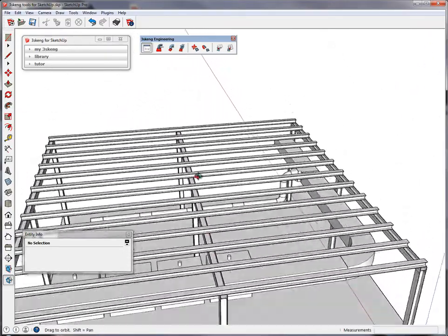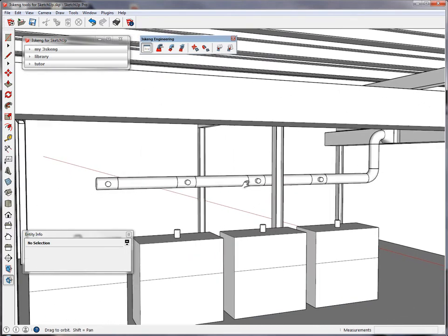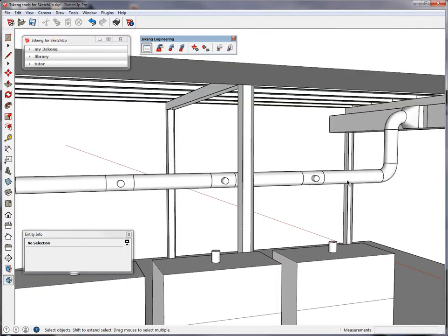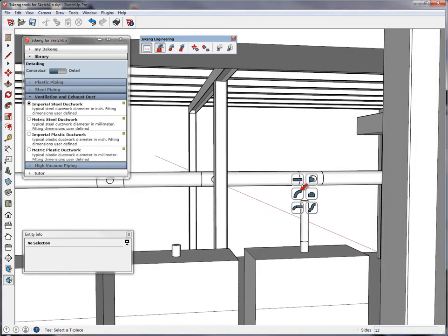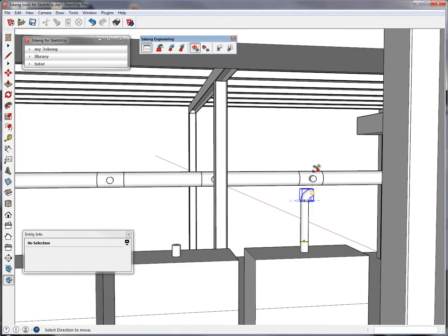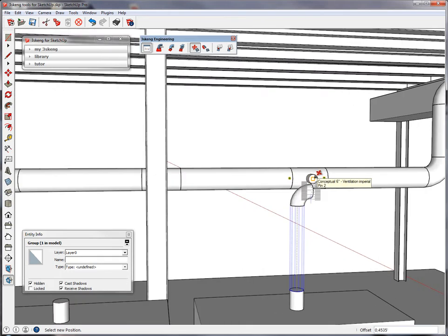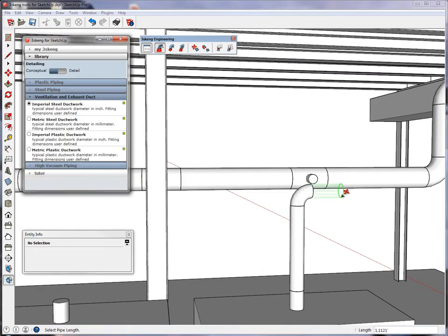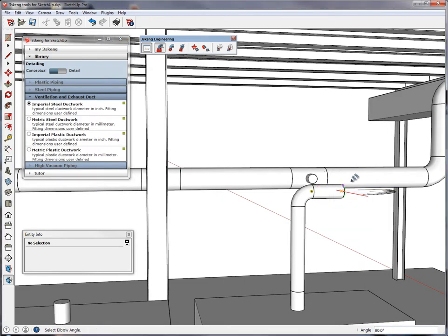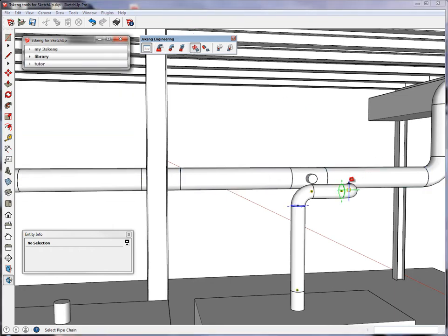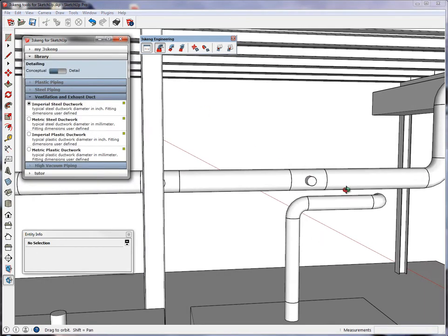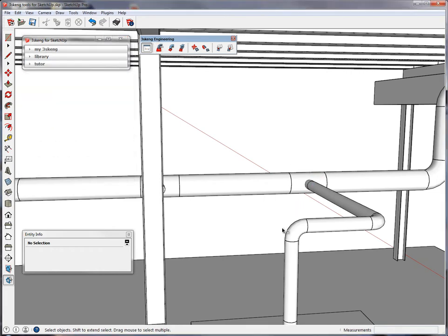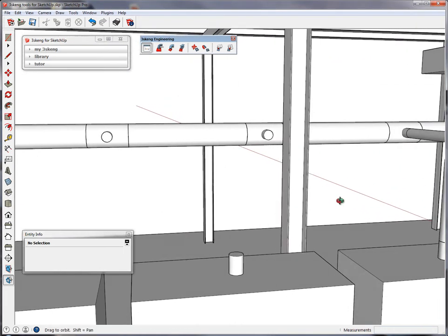To connect the fume hoods to the outlets, we basically have 4 possibilities. The first possibility is what we started out with. You just draw a straight pipeline, add an elbow, edit it to the appropriate height by catching this pin, add another straight piece, add another reducer facing towards this, 90 degrees, edit this one to catch this outlet, and do the final connection here. To be honest, it is quite fast, but it never seemed fast enough for us.